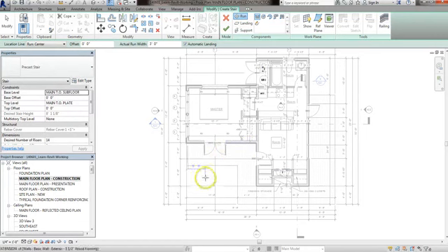Well, it's actually going to be from a base level, which is going to be our top of foundation, up to our main top of subfloor. But if you know about construction, normally you have your base level, let's say you have it at top of the foundation. Normally the earth is 6 inches below that. 6 inches.